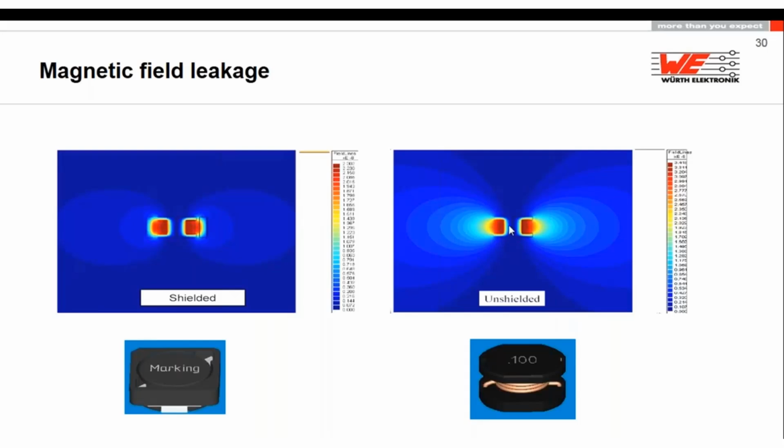It has an infinite air gap. The air gap at the shielded inductance is on the top and the bottom. We need this air gap because we don't want to saturate the inductance. But if you look at the magnetic field generated by a shielded inductance, the big magnetic field will not take the air, because air is not so good magnetically conductive. It takes this way through the shield and comes back, but it will have some leakage anyhow. Because of this reason, don't route any track below the inductance on the same layer, because this is dangerous.